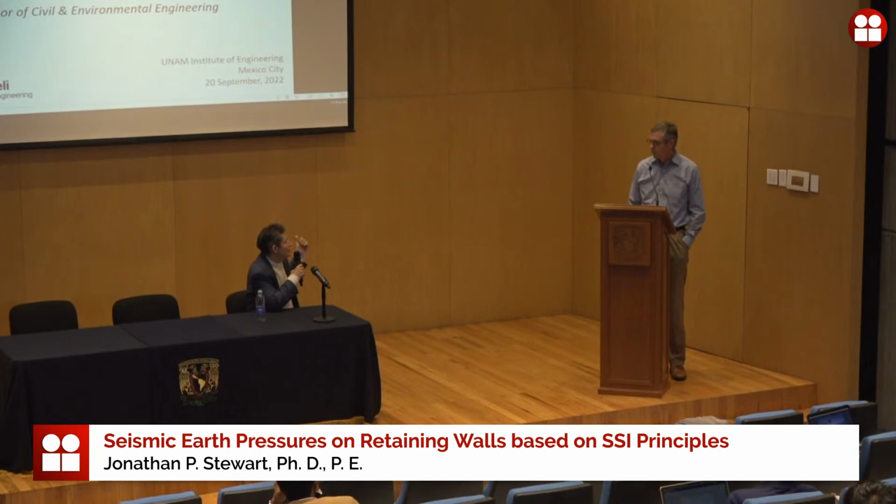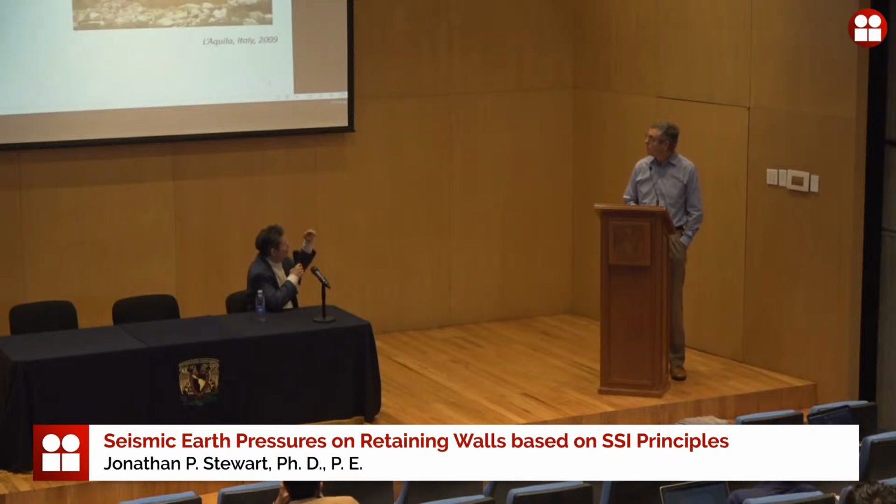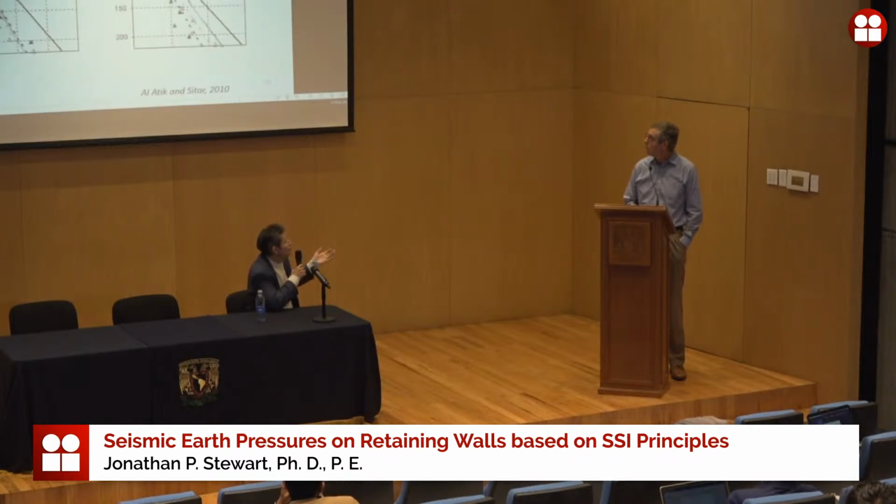I'm talking about the retaining wall. I mean, we usually use piles combined with truss to make a flexible wall when we are working on excavation. Here, you know, you are plotting a typical retaining wall for a road or something. But in practice, you actually have piles that are connected to a beam.